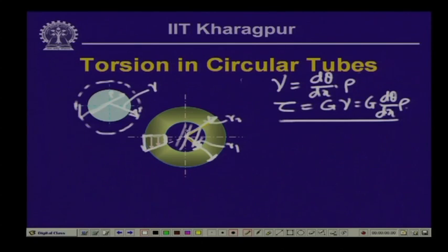So, on any cross section the stress resultant is equal to the applied twisting moment, and the same concept we apply here to evaluate what should be the relationship between the stress and the twisting moment. Now, let us consider a small element from the center, which is at a distance of rho and making a small angle, let us say d alpha.